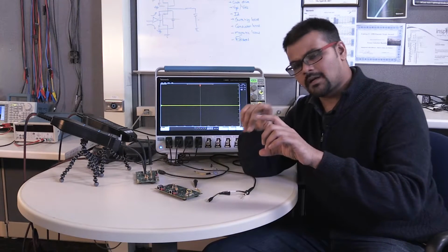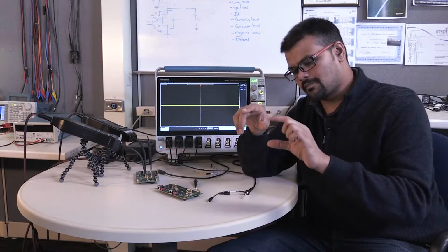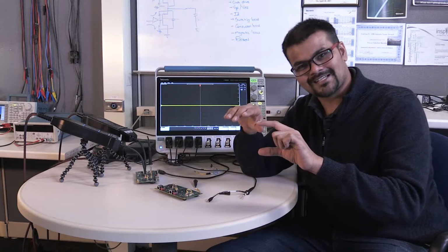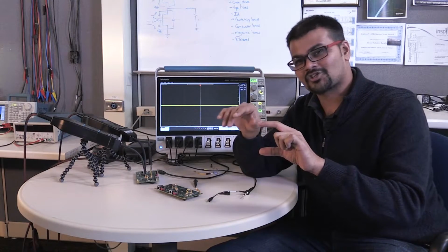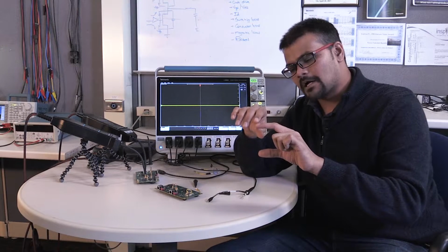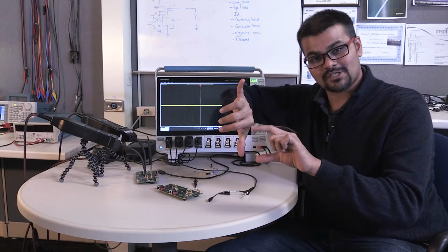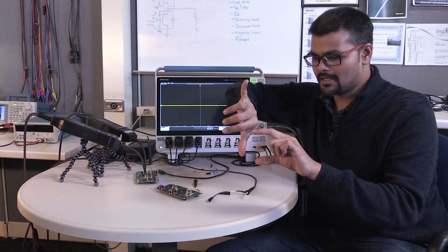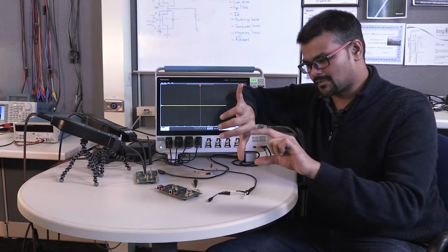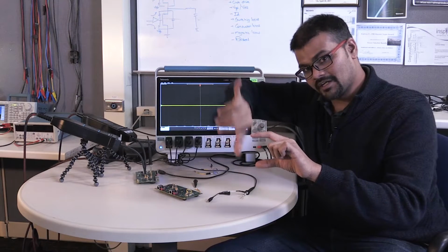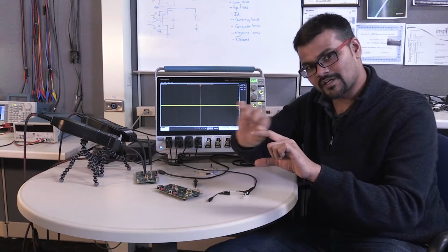The other piece of it is, think about the measurements we are trying to make. We are trying to measure what's happening on VGS. We are trying to measure what's happening on the shunt. We are trying to measure the gate charge and so on in presence of a VDS measurement, which is 400 to 600 volts. So if you think about this problem, the vertical resolution you need has to be really high if you really want to see details on this.